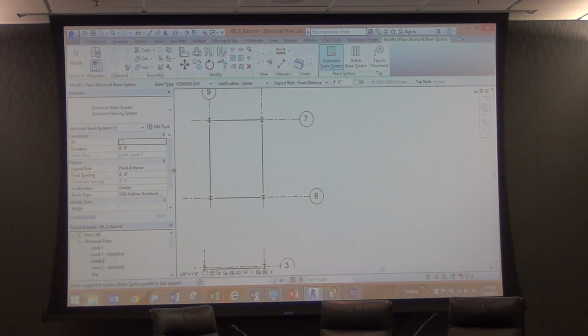I'm just going to put in a beam system. Beam system works fine, at least in my experience. I guess I didn't test if you moved things around in that beam system, if that breaks it. I would guess that it does because it's a pinned member, but it doesn't seem to affect it when you're updating members and reactions and things like that. It seems to come over fine. I'll do 4 feet, I don't know how big that bay is.